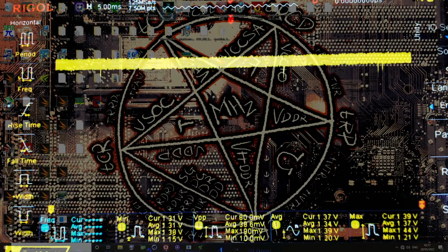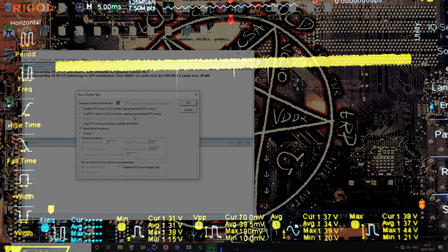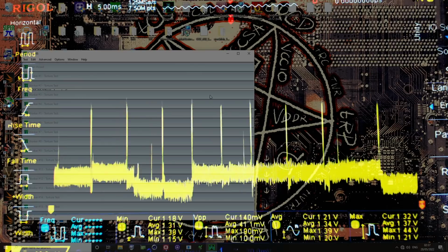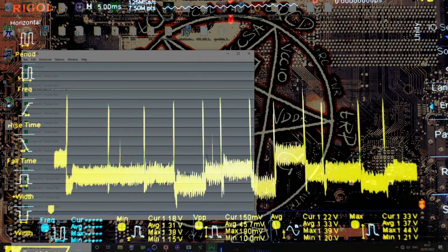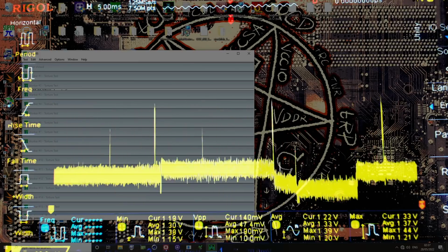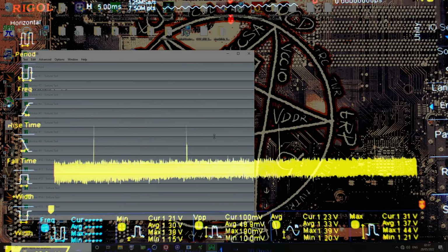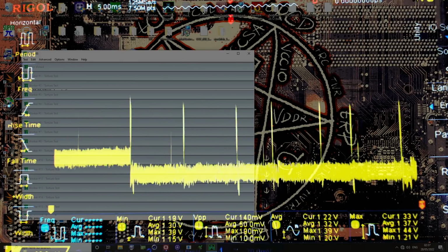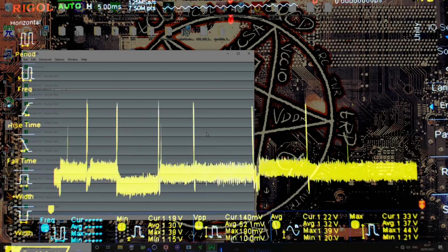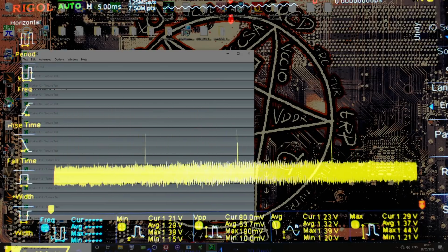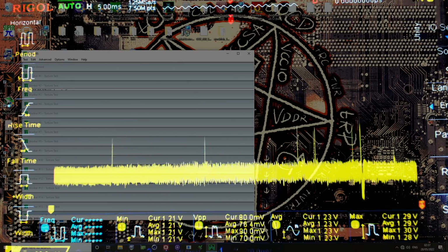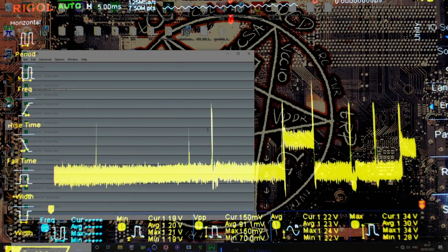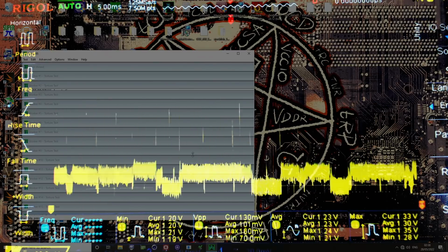Okay, let's hit it with Prime95 small FFTs. I'm getting 1.2. No, it's still... It's nowhere near as bad as it was at 1,000 kilohertz, but it's still... So if I don't move the mouse, the minimum voltage is 1.21 volts. And then it... Yeah, okay, now this is not okay.